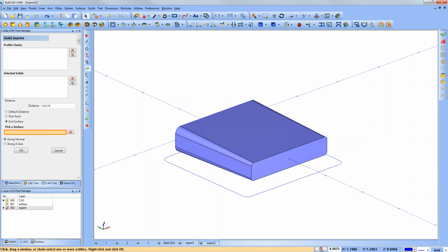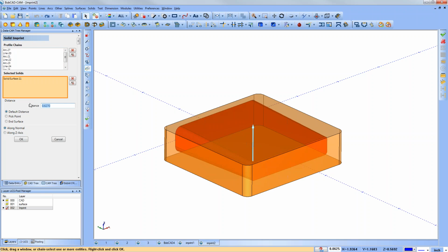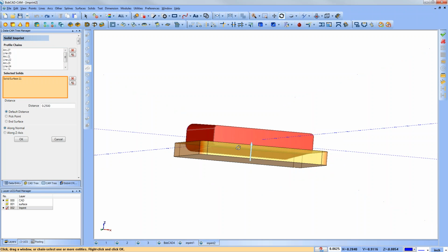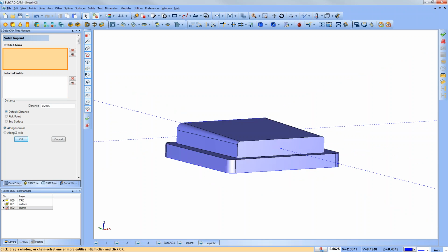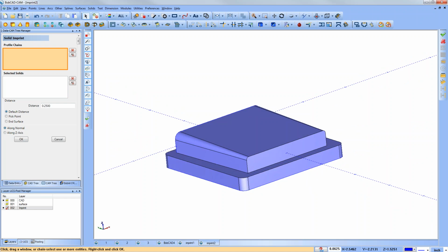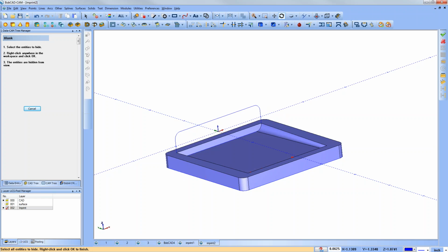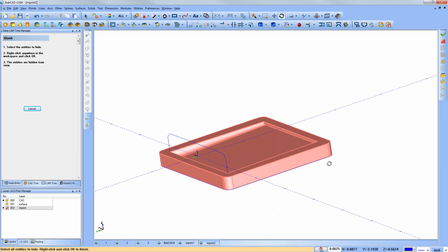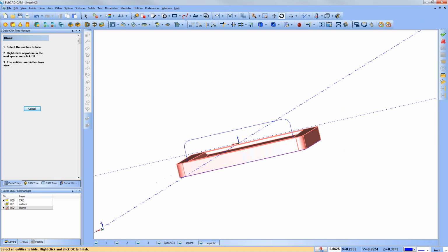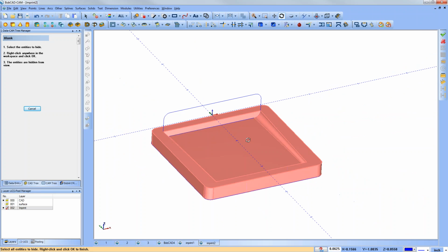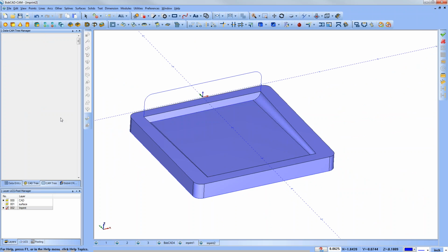I can use that surface. Otherwise, what that would look like is kind of like the first part. So picking our chain, picking our solid, and then picking our distance. I'm not sure how high that is. Let's say something like that, right? Then that would be the other result, the alternate result, like you saw in the first part. So it's a useful function, only the top surface is flat, because I've brought it to a consistent extrusion distance. Anybody got questions on that?